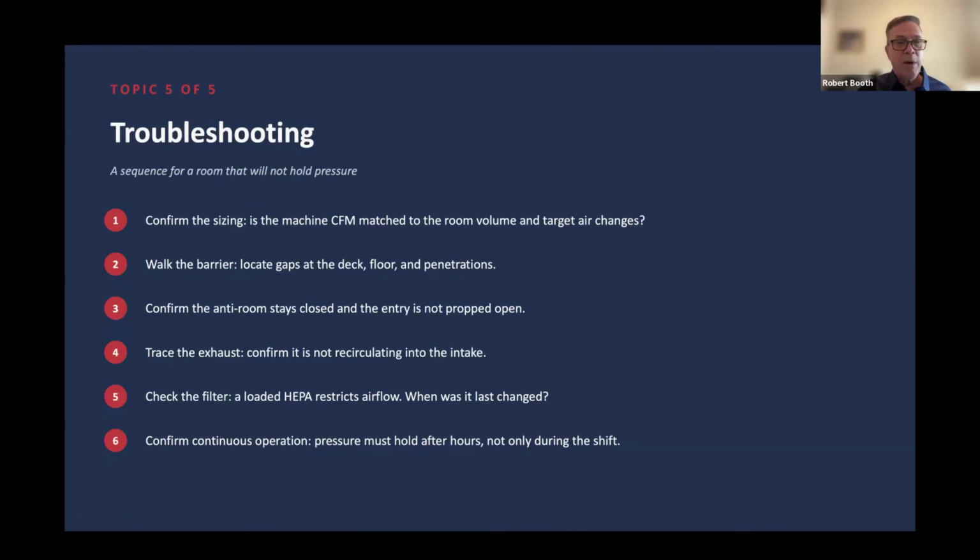So back to what we talked about earlier in the presentation, you should really plan for what that negative air system should look like, meaning what kind of negative air machines I'm going to use, how many air changes I'm going to desire, and what I'm going to have at the end of the project to make sure I can get that done. One thing that we see with delays is that the facility is ready to take down precautions, right? And they're done with the work. But the policy says you should have this many CFMs, and the contractor didn't really do that very well.